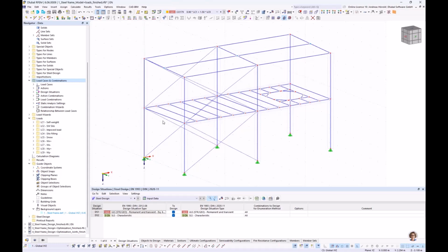But if you would like to do that, I do it for the horizontal beams of the frame, and the same workflow would be necessary for the platform beams. But we don't do it for them because of the steel plates that are screwed on the flange of the members.